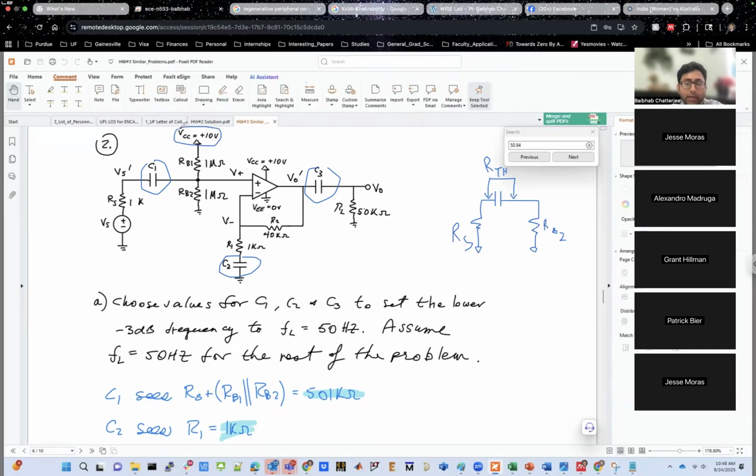However, keep in mind that Thevenin equivalent resistances will be used for AC analysis in this case. And of course, you are doing an AC analysis because you are looking for the pole. The pole is an AC concept. At DC, there's no concept of poles. So if you're doing AC analysis, in terms of AC, all your DC voltages are virtual ground.